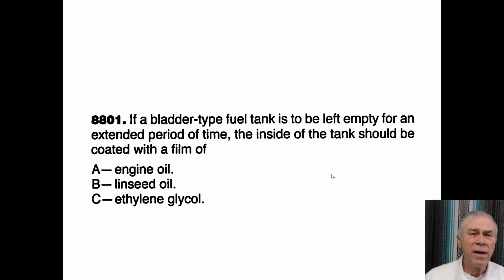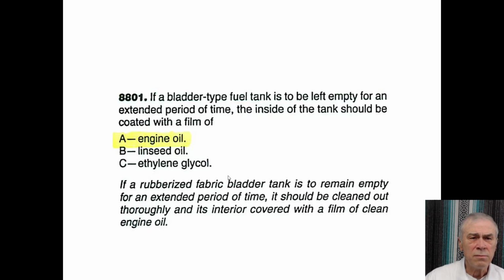All right, if a bladder type fuel tank is to be left empty for an extended period of time, the inside of the tank should be coated with a film of, was that engine oil, linseed oil, or ethylene glycol? That was engine oil. A film of clean engine oil.